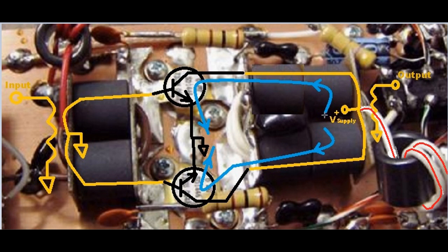And we're going to see shortly that again we have a single supply with two paths to ground. It wants to go from a high potential to ground. It can either go this way through the upper transistor or this way around through the lower transistor. And we're going to see that these two transistors are going to be alternating for each half cycle of our input signal. So now let's go back to a circuit diagram and understand the operation of this implemented push-pull amplifier stage.